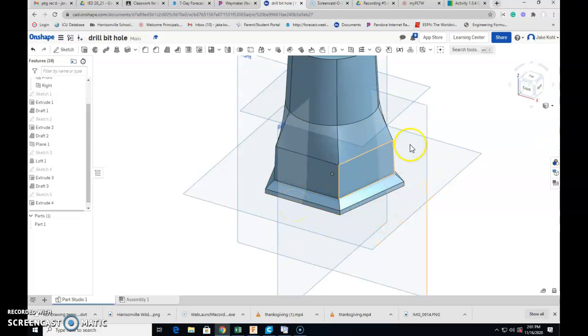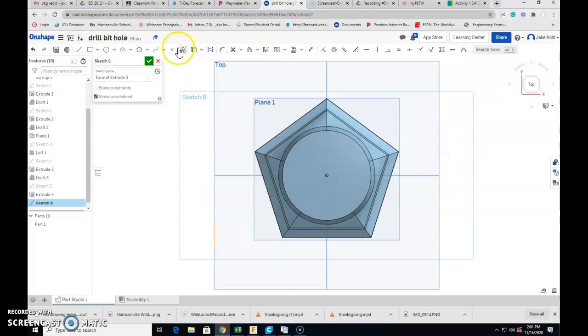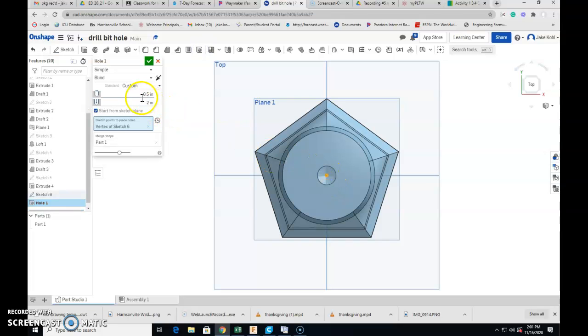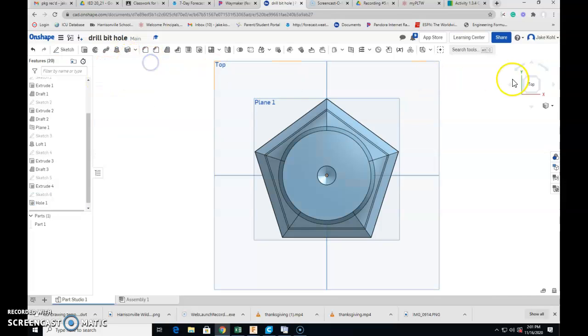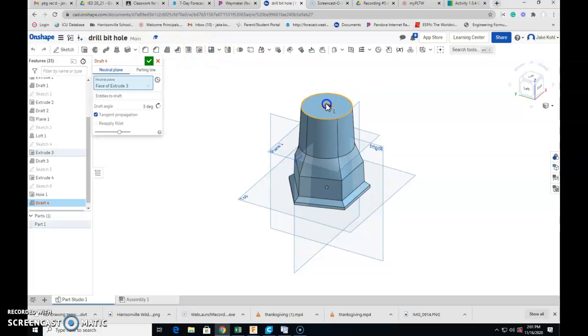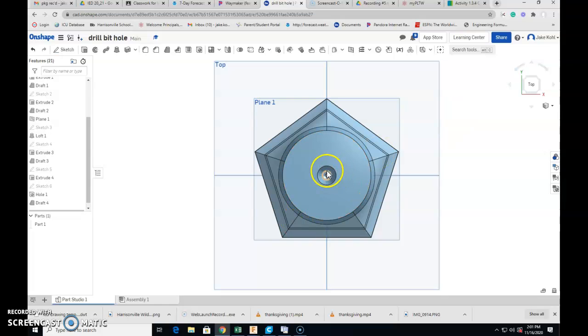Okay, next thing is the hole on top. So, sketch, boom. All you really need is a dot or point, and then you can use that. And go to 2.5. Down. There's our big hole. We're supposed to taper that as well. So we can click on that and then that. And it tapered that hole. See how it's gradually going in.